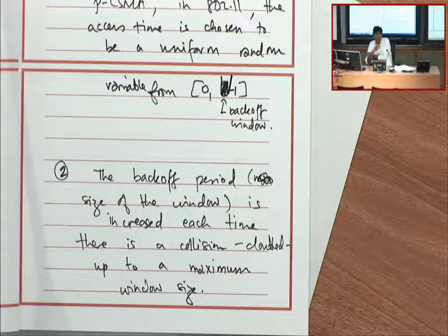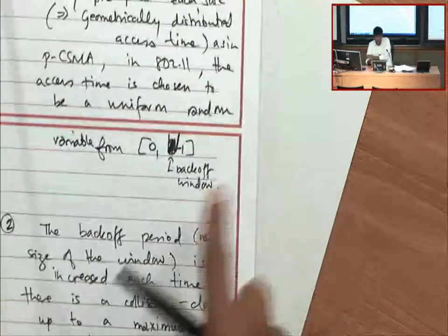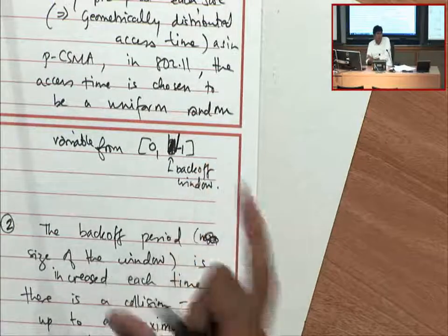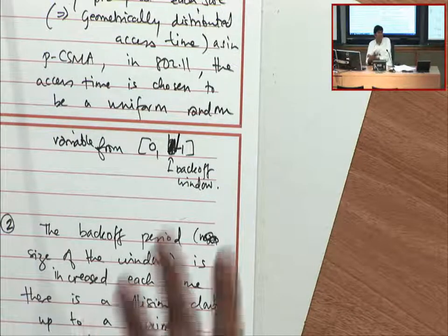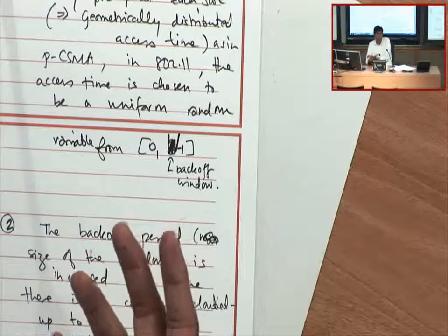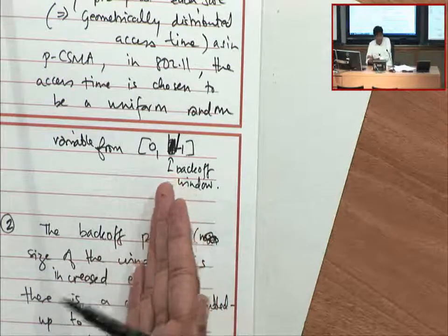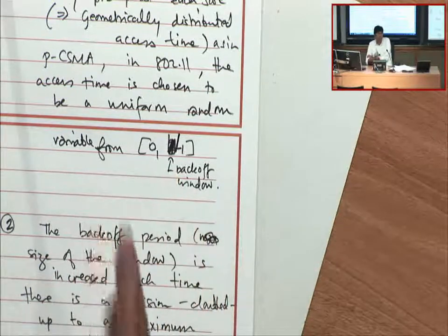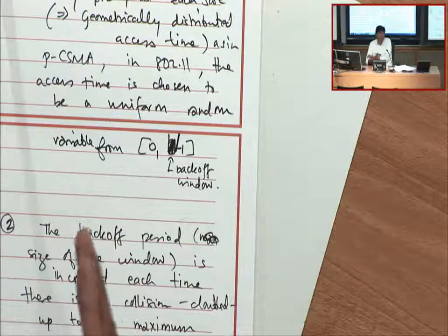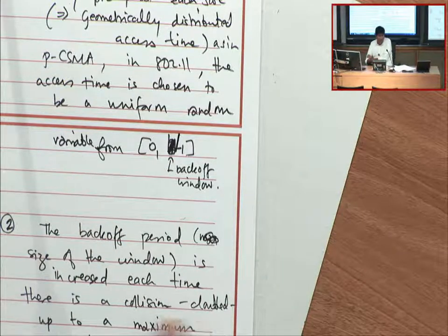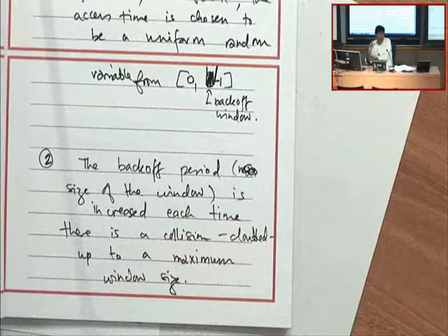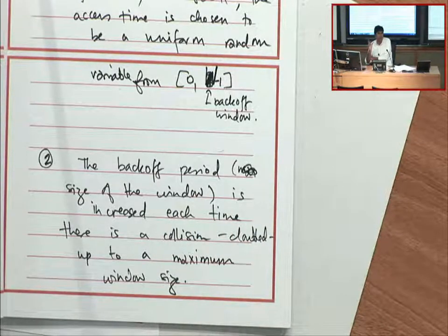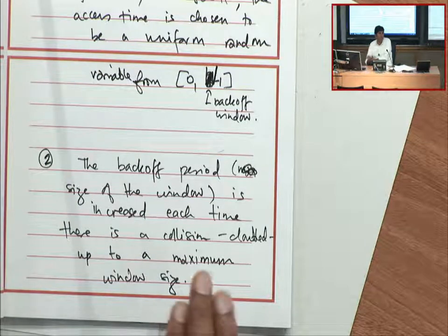There's a couple of reasons for this. One is that your initial back-off window might be kind of small, just to reduce your deterministic latency if there are no collisions, if there's no interference. On the other hand, because it's a finite number, if that number is too small, you'll keep colliding. Chances are very high that you'll keep colliding. And so by allowing for this possibility, you're almost balancing in part for the fact that it's a finite window. So you might need to make that window larger to avoid collision. So that's what this is doing.